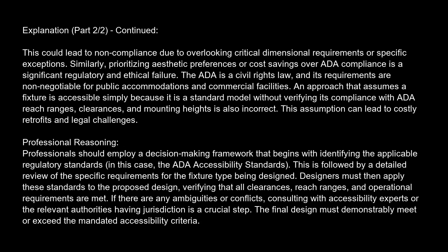The ADA is a civil rights law, and its requirements are non-negotiable for public accommodations and commercial facilities. An approach that assumes a fixture is accessible simply because it is a standard model, without verifying its compliance with ADA reach ranges, clearances, and mounting heights, is also incorrect.